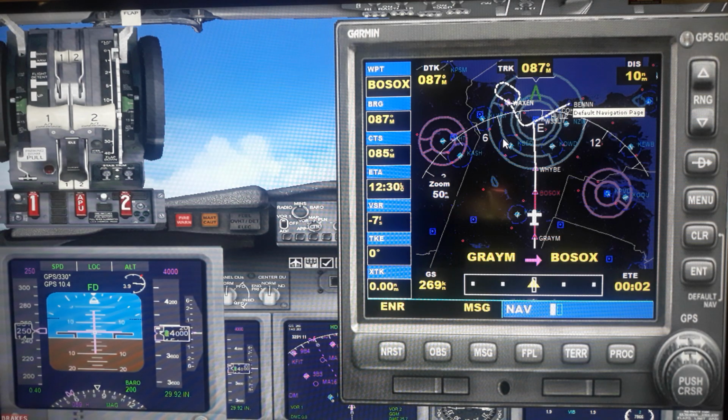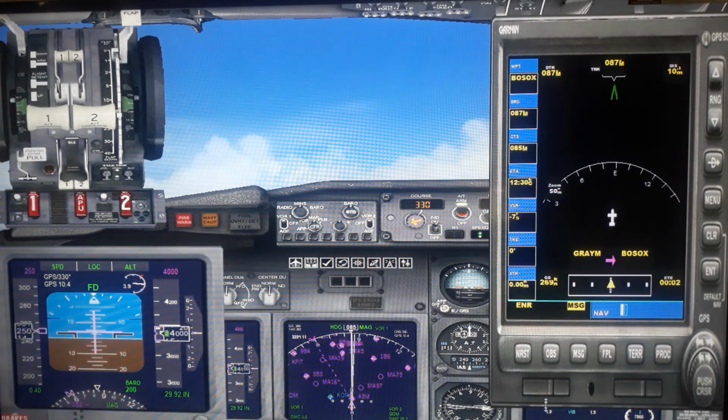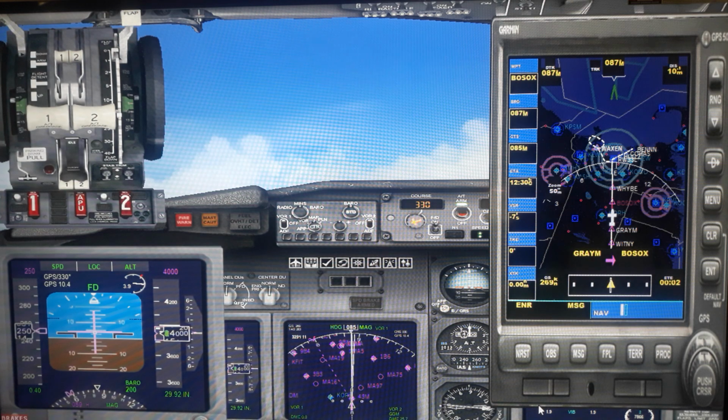You keep doing everything required. There are so many things to do, like adjusting the flaps, the speeds, and all that stuff. We'll see that. So this is going to be a lengthy video. I'm sure of that, but this 1 hour please spend, and we can again go back to look at every aspect. Now the GPS itself we can go for a week, and there are other navigations, VOR navigation, so many things. But okay, now we will close this. We'll put it back to the original size and resume our flight. All that we need to do is to activate the approach. I have set up everything, but short of activating the approach to Benin.